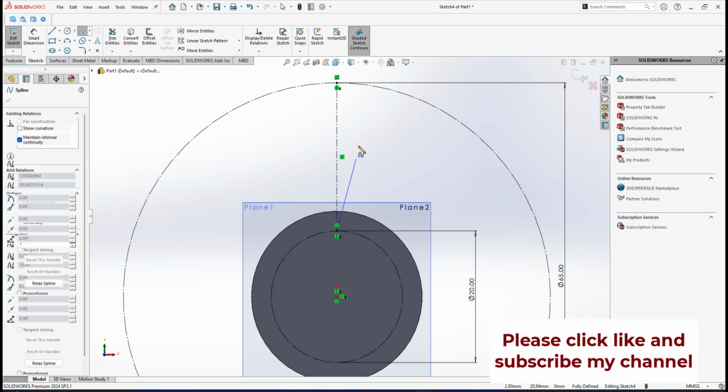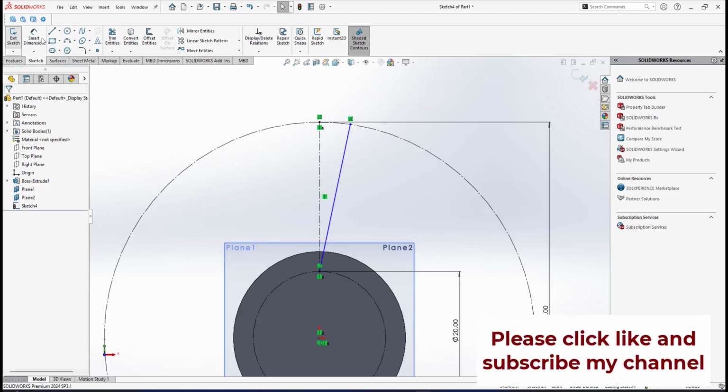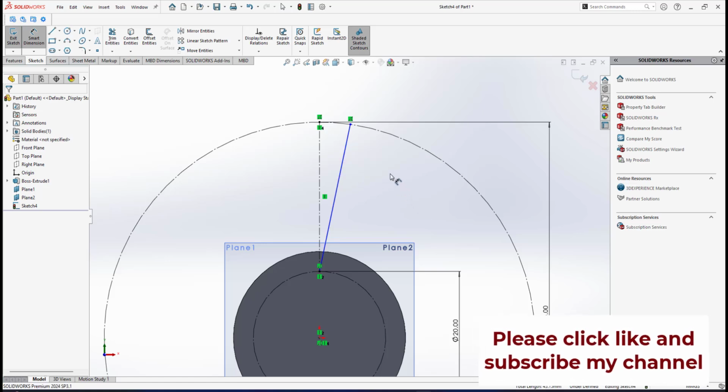I will start at this point, just a 2-point spline. I will go like this. Right. Okay, spline, I cannot put an angle. If I try to put a spline, it's not a straight line. If I put an angle from here to here, I cannot put an angle. So what I can do for the spline, I want to make this spline fully defined.